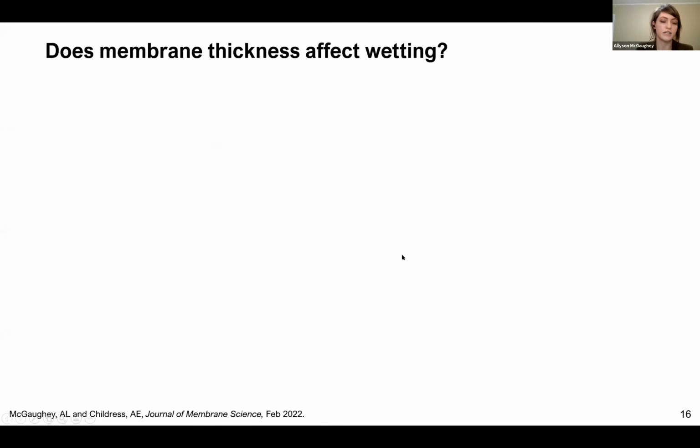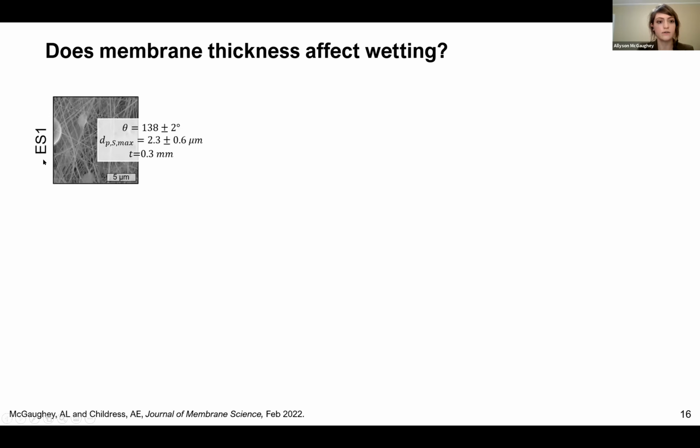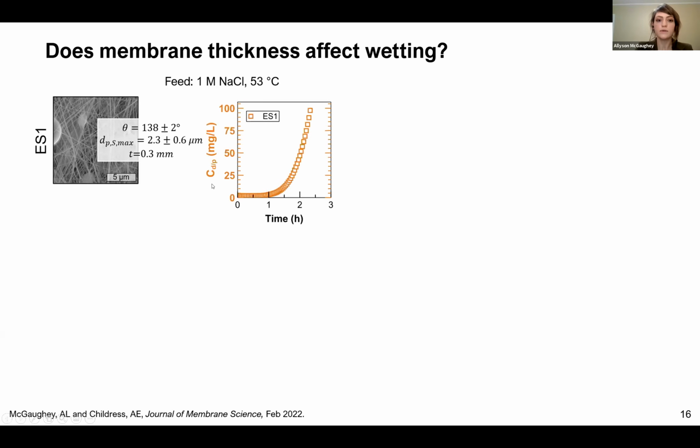And the last thing I want to mention today is looking at how membrane thickness affected wetting. So for this, we used electrospun membranes. And here I'm showing the contact angle, maximum surface pore size again, and also the membrane thickness. And we tested these again under our baseline conditions. So here we see results for CDP versus time. And we see that this membrane wetted relatively quickly after just about an hour of operation,